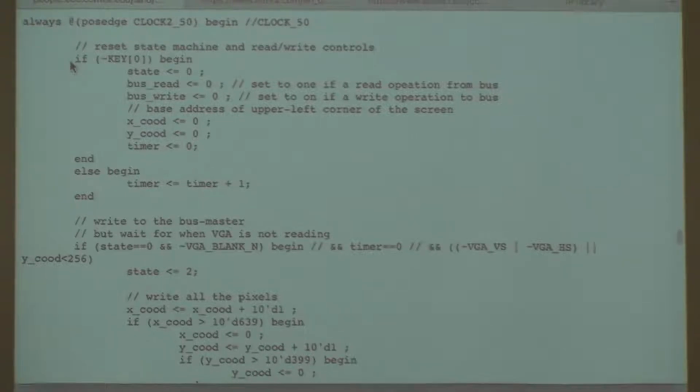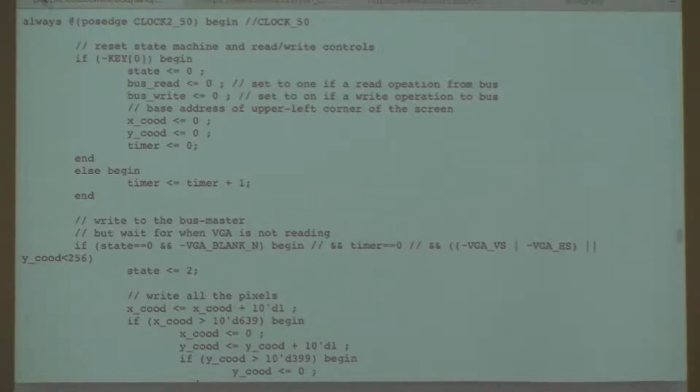The write takes 2 bus cycles. It takes 1 bus cycle to set up the write, and then another bus cycle to check for the ACK. And because you're overlapping 2 bus cycles, you may be overlapping a pixel requirement, a read requirement of the SRAM from the VGA controller. And so this code will fail with a shimmering display. The sync will be shaky or worse.